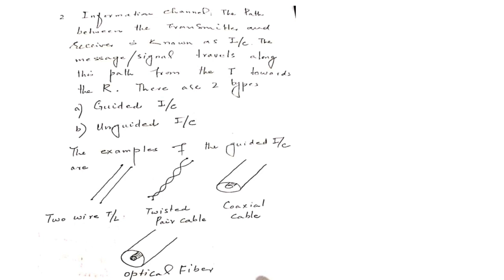We do it with the help of amplifiers or repeaters. We will use an amplifier in the information channel to amplify the signal. In case of a fiber optic communication system, we will use optical amplifiers. Anyhow, optical fiber does not attenuate the signal too much, so fewer amplifiers will be required in a fiber optic communication system as compared to the traditional electronic communication system.